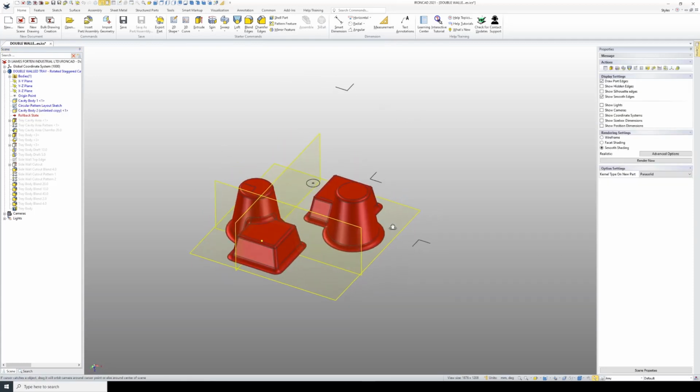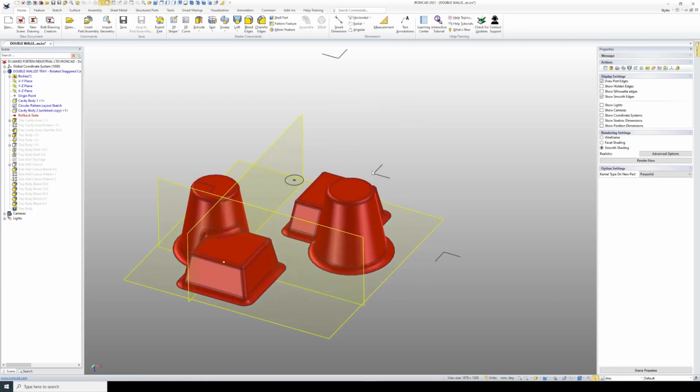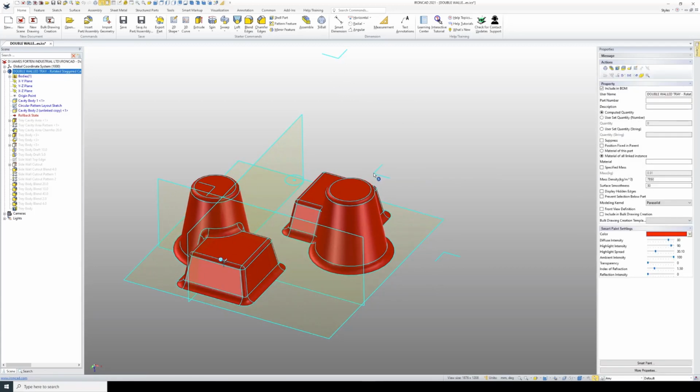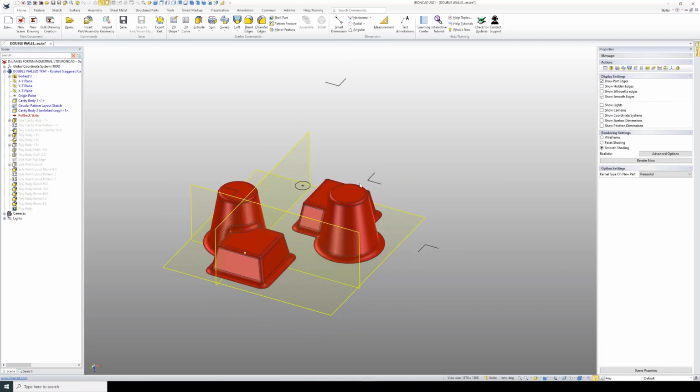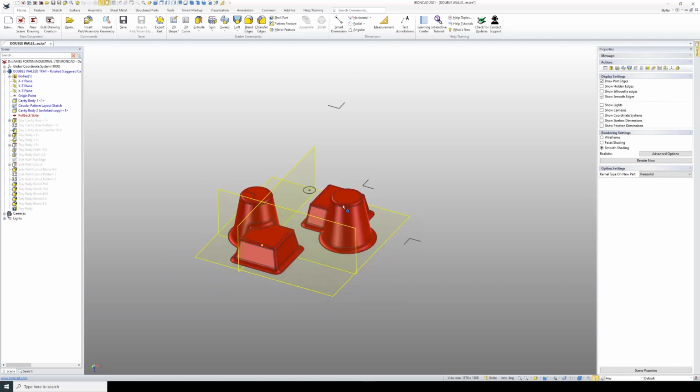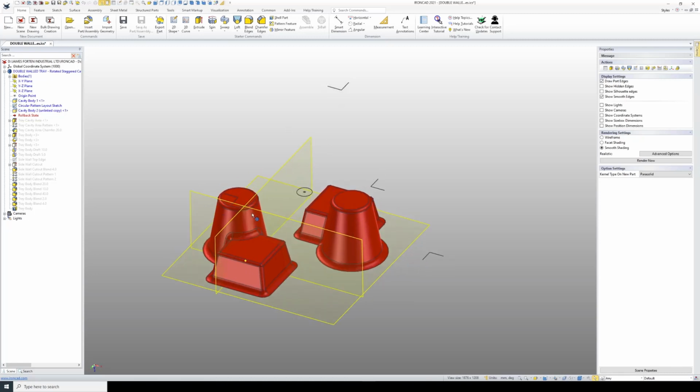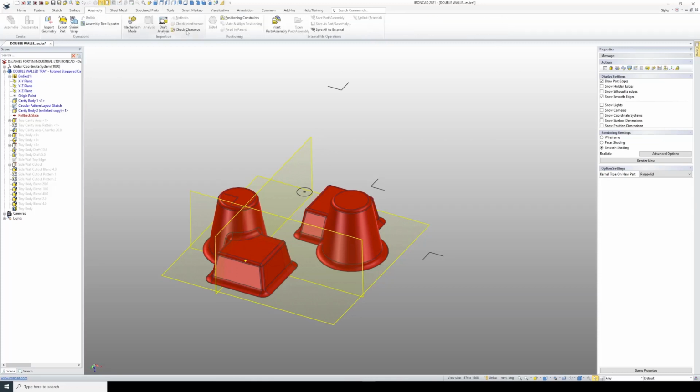So now I want to lock this second body to this point on my sketch, because the purpose of this sketch is to control the positioning of this second body, but we're also going to use the sketch for driving the other patterns that are going to follow. So within IronCAD, within the assembly tab, we have positioning constraints. And these are used for positioning of solids and surfaces to each other, but they don't work with sketches.